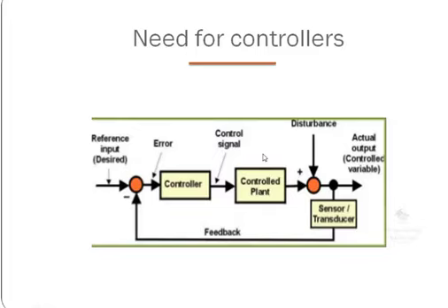The final control element is the one responsible for getting the command signal from the controller, which means your control signal, and it will take the order from the controller and execute the order of the controller. So whatever is decided by the controller, this final control element will execute that, and that output will be taken as feedback in order to compare with the set point. So our controller plays the crucial role. What control action has to be taken will be decided by this controller.